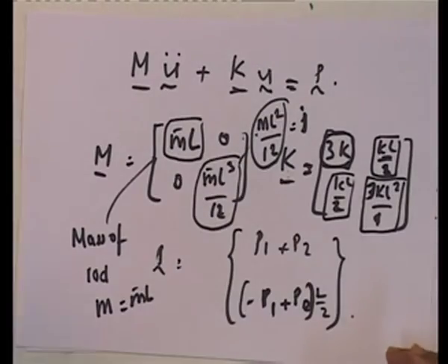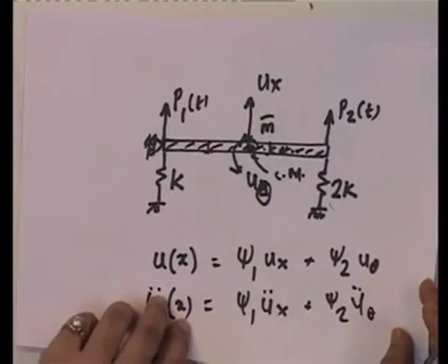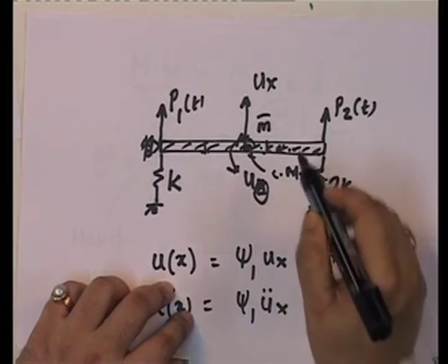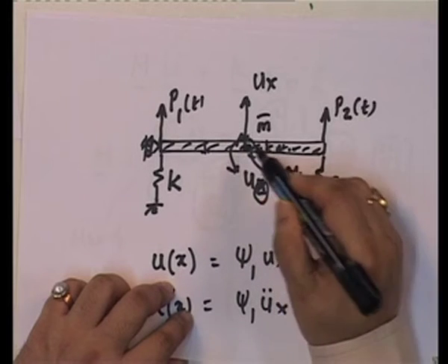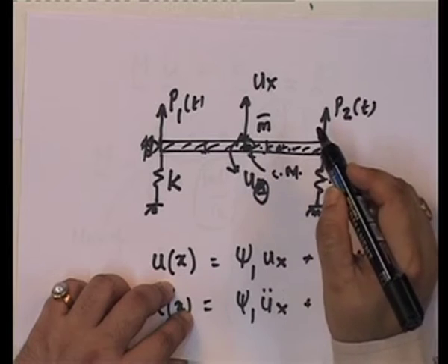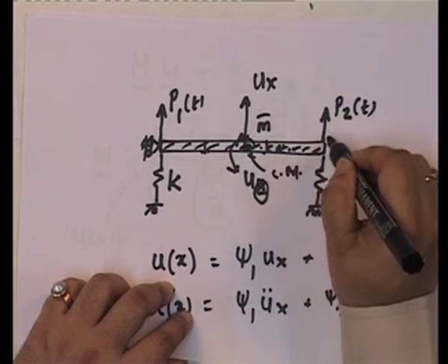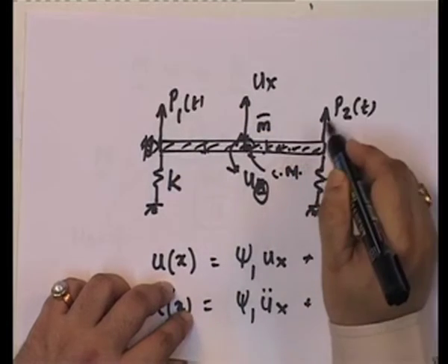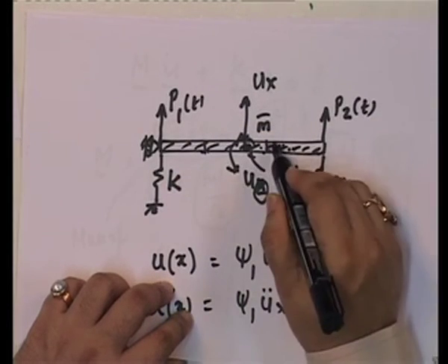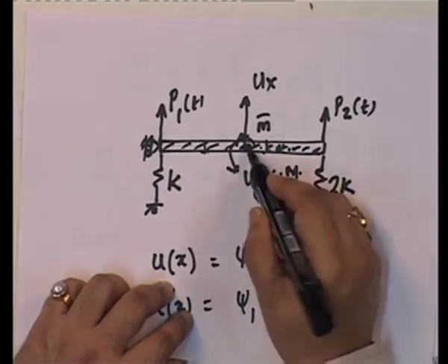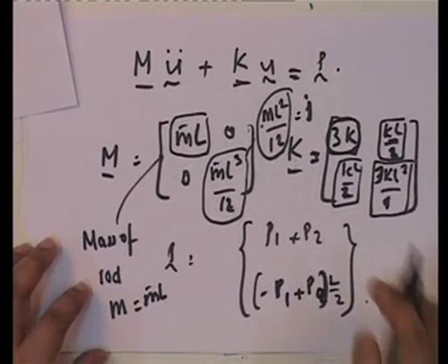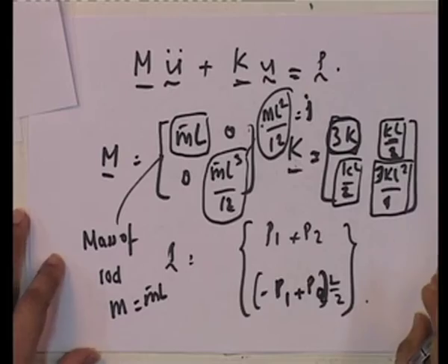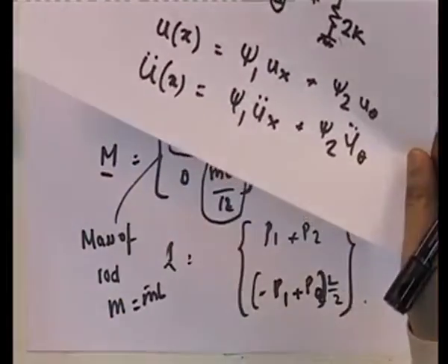So, these all have physical meaning, and if you look at P1 and P2, and if I have the center, P1 plus P2 is the load, and what is the net moment? P2, see this one has negative, okay, this has positive. So, this is P2 into L by 2 minus P1 into L by 2, which is the net moment here. That is what we have. So, you see all of these terms have physical significance in the entire scope of this, and therefore, coming back to it, if we look at it,